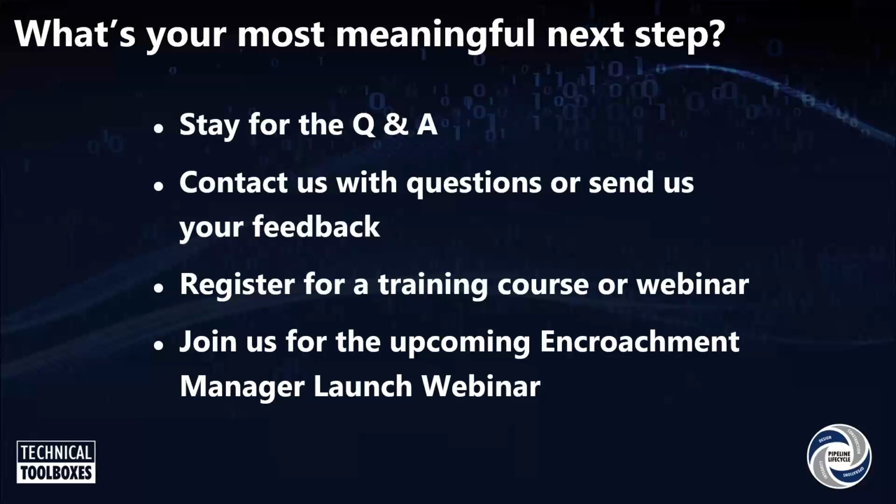Absolutely. That's a great question. Yes, when you have resistivities such as in brackish water, the voltages needed to create a corrosive AC environment are going to be less than a volt. I never ran into 5 ohm centimeter water, but I've run into 30 ohm, and you could have half a volt of AC voltage and have a corrosive condition.